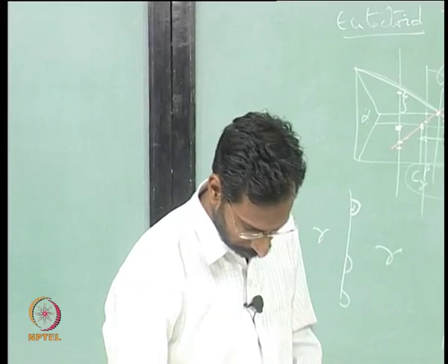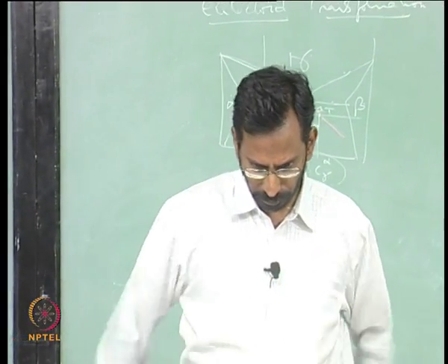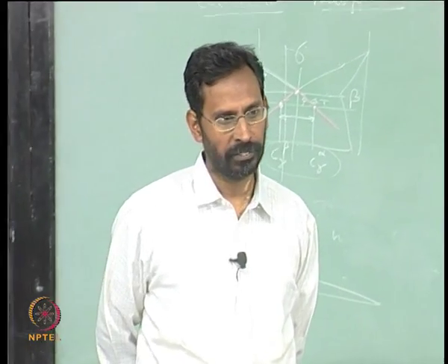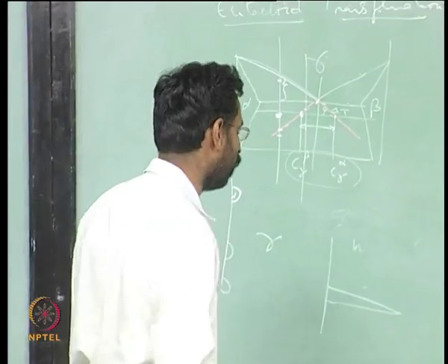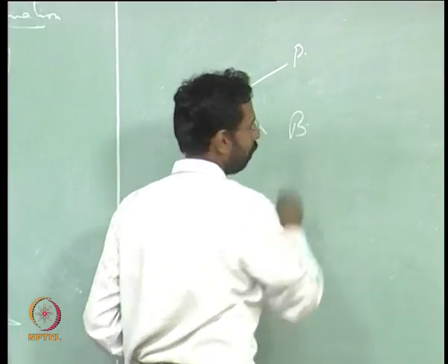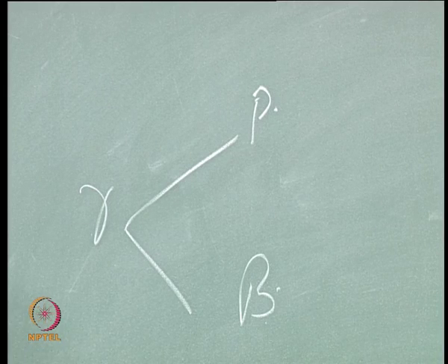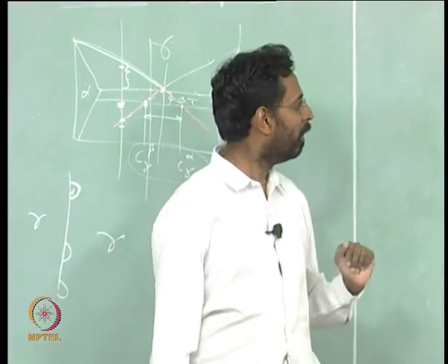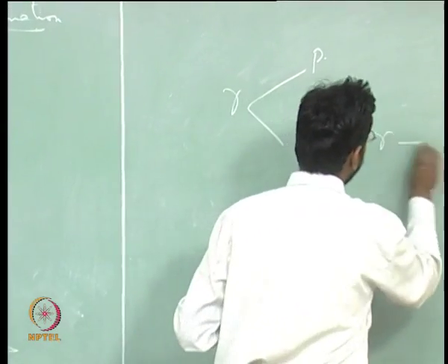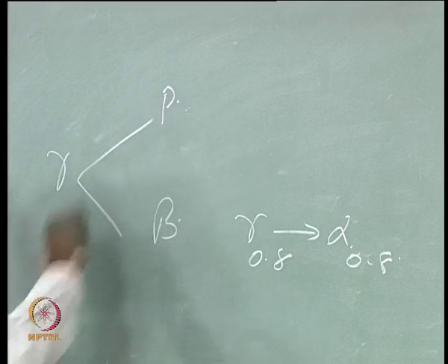The ferrite is the active nucleus. Yes. And in the eutectoid, it is the ferrite formation, it is the cementite. Why is there a difference? Again, it is not very difficult to understand. See, if you look at the two transformations, gamma giving pearlite, gamma giving bainite. In gamma giving bainite we have undercooled to such an extent that the carbon is not able to move much. Because carbon is not able to move much, long range diffusion is difficult, though short range it can possibly still do. As a result, gamma first becomes alpha of the same composition, polymorphous.